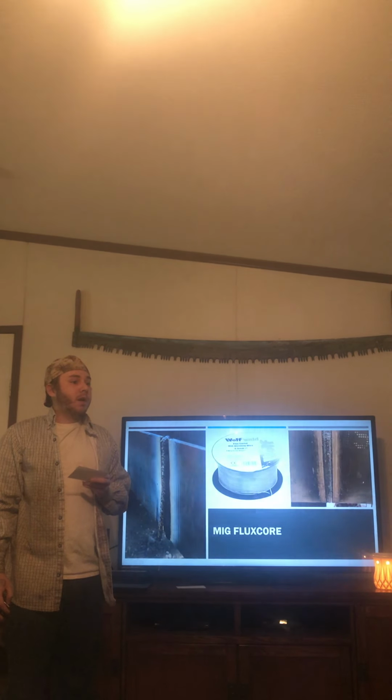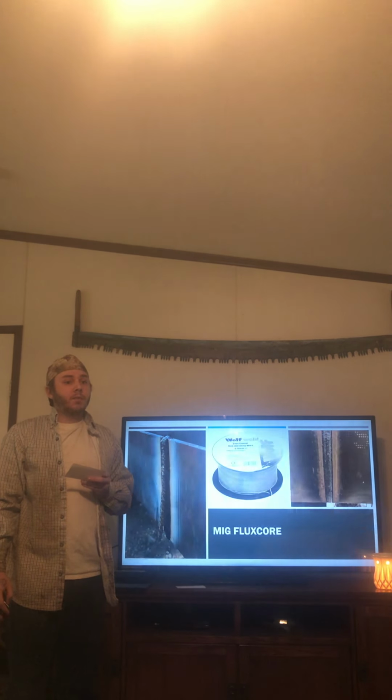The beads are much wider than most stick welds, and the characteristics of the dual shield flux core can penetrate through rust and heavy mill scale. For structural fabrication, shop workers need to be able to make quick work of I-beam projects, and stick welding can be a real hassle with that kind of thing. To avoid rod stubs all over the floor and constant replacement of rods, using dual shielding instead can skyrocket the productivity of beam fabrication. If you are fabricating on a strict time frame and must maximize the working hours in a day, dual shield is really worth looking into.